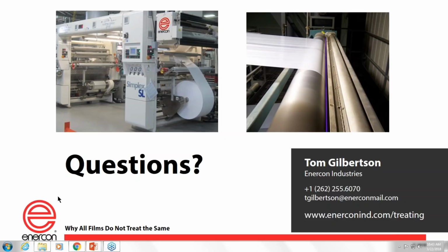It'll start to gather a bunch of static, or it'll pucker, or it'll wrinkle or something. And as a result of that, the dyne number went way up, if you did a dyne test. But really, that's not what you're concerned about. Because you apply so much power to the web, the web itself kind of reacted in a negative way, thereby causing you other application problems. So in that particular sense, one could say, yeah, a high dyne number caused this problem. It's really the power that we're applying to get the high dyne number that's causing the malady. So typically dyne numbers in and of themselves don't cause the problem, but the correlating effect of applying the power to get the high dyne number causes a problem.